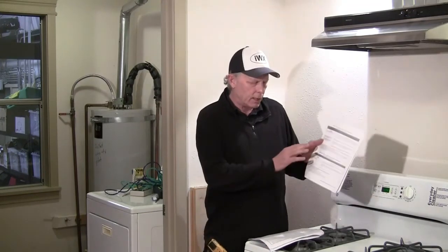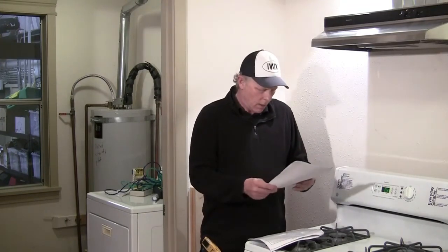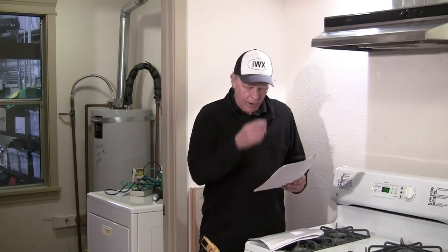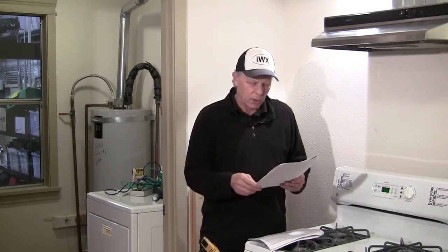We're at 240, so we have an unacceptable level. I would find my action for unacceptable levels on table D1B, and it says that we need to advise the homeowner or occupant that the appliance should be serviced immediately by a qualified professional.